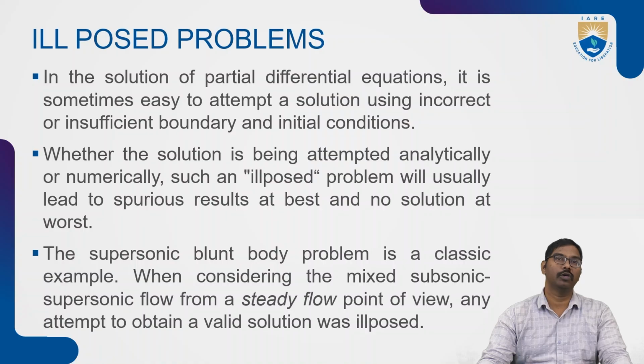So we have discussed how the partial differential equation, the governing equation of the fluid flow behavior, is going to affect the CFD approaches. We have differentiated the PDEs into elliptic, parabolic, and hyperbolic based upon the roots of the characteristic lines, or based upon the eigenvalues. And we have also seen some examples of how different flow problems, defined by different governing equations, have different forms of behavior.